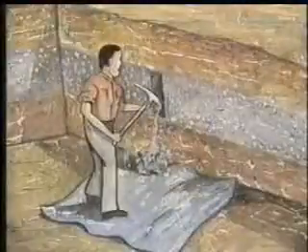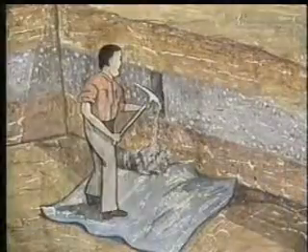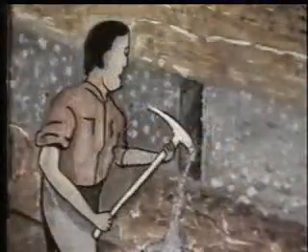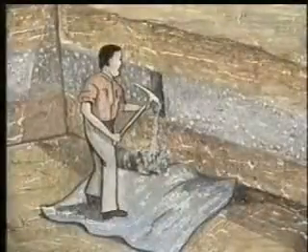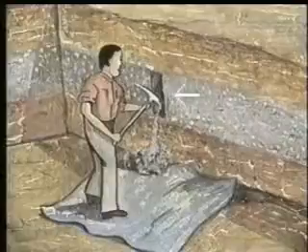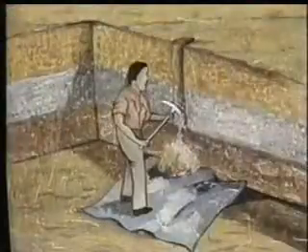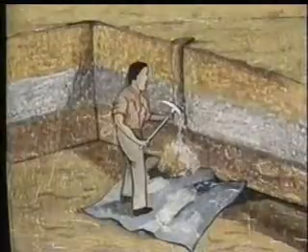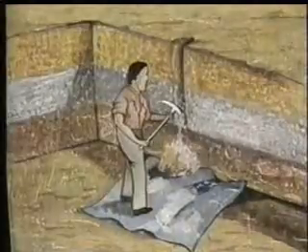Samples by this method can be collected economically up to a depth of 6 meters. Disturbed sample may either be individual or composite type. An individual sample is one in which soil is obtained from a single layer at the same depth. To obtain composite sample, soil is trenched down the vertical face of the pit from different layers.